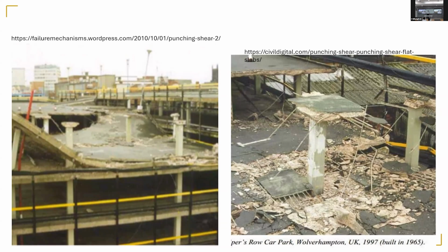So this slab basically carried about 3 times the design load that it was designed for. Of course, there is no 3 times margin in that one. So this slab at this point actually had a punching shear failure. So this fell down on this one, this fell down on that one, and then everything fell down. Okay. So the important point is that when you do the casting of these slabs, you must support the slab below all the way.